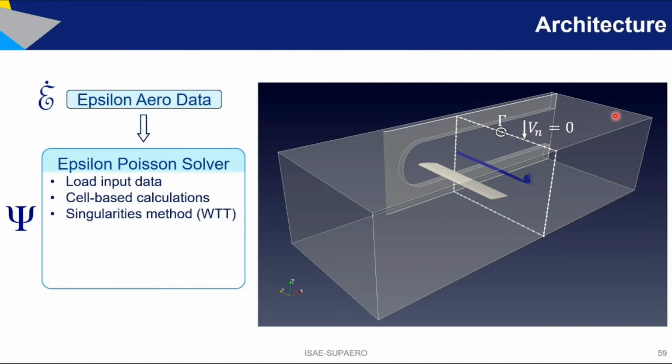So with this information in hand, you can solve a linear matrix solution that will give you the intensity of gamma at each one of these wall panels, and this will give you the distribution of vorticity, of circulation, at the wall that allows you to deform the stream function, taking into account the presence of the wall when you try to compute the vortex drag.